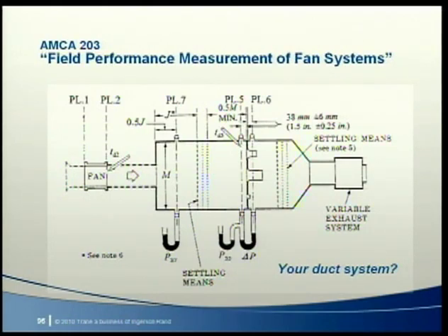AMCA 203 includes detailed guidance for designing and performing field tests. Taking measurements in the field can be difficult, and you don't always have access to the right measurement location. So it's key to understand how to make necessary corrections. But field performance tests are never easy and not nearly as accurate as lab tests. So although verifying fan performance in the field is not impossible, it's probably not your first course of action for correcting airflow shortfalls. And now for some thoughts about noise.